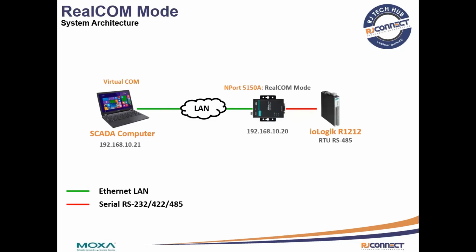Okay, here is the system architecture of the RealCOM operation mode using the NPORT 5150A to access the RTU RS-485 device, which is our iLogic RS-1212 for RTU RS-485 device. So I will just show you guys quickly.